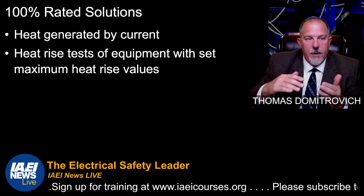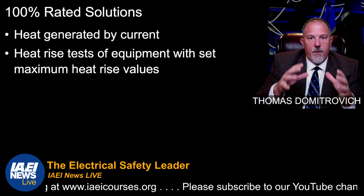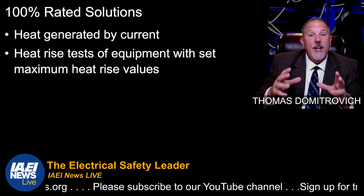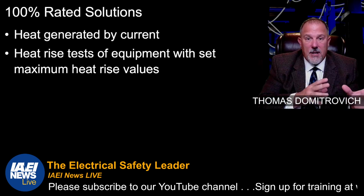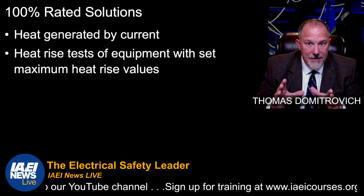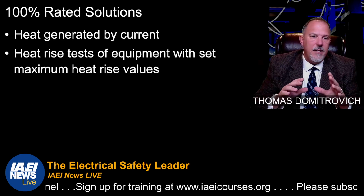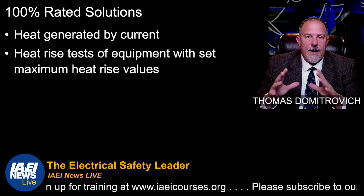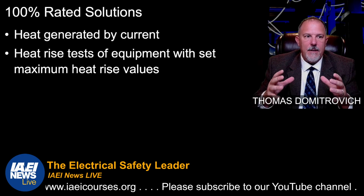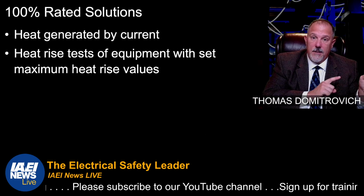What we look for is a temperature rise within those terminations, within whatever I'm monitoring inside of that enclosure. What we're going to talk about is in regard to the overcurrent protective device. But this whole concept of 100% versus 80%, the 1.25, is a heat rise concern, not just for overcurrent protective devices.